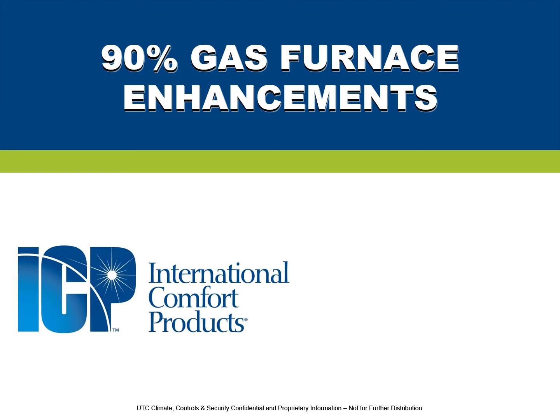Furnace orientation is another aspect that directly impacts efficiency. If you have a furnace being installed in a horizontal application, whether it be horizontal left, horizontal right, or downflow, these also directly impact a steady state efficiency reading. A furnace might not perform the way that it does in an upflow position as it would in a horizontal left, horizontal right, or even a downflow position, because there are changes in the application that directly impact those readings and efficiencies.